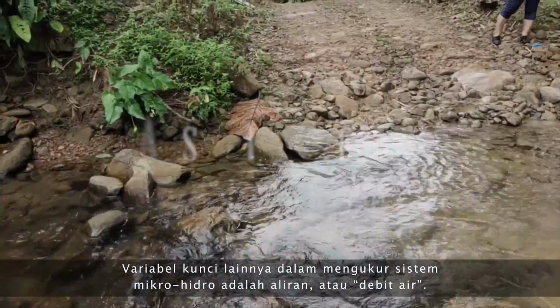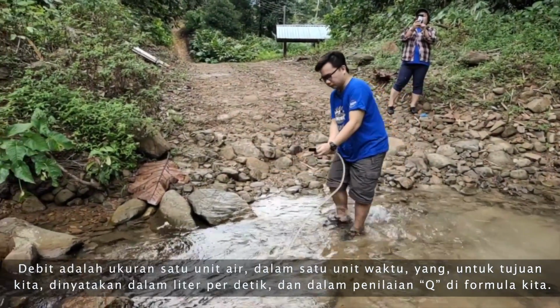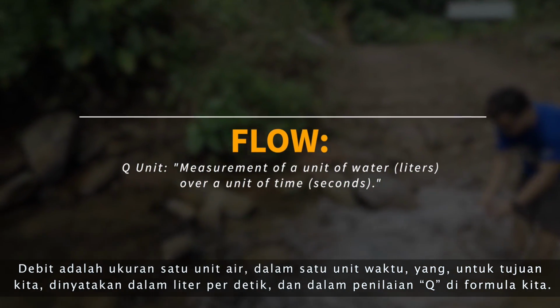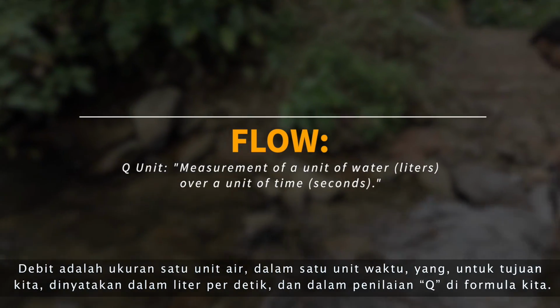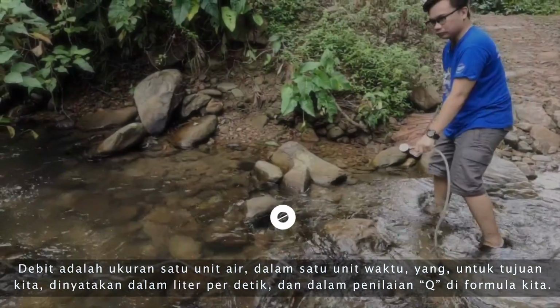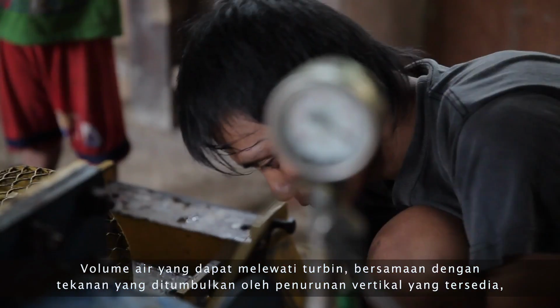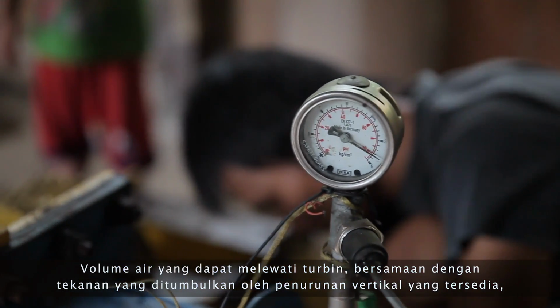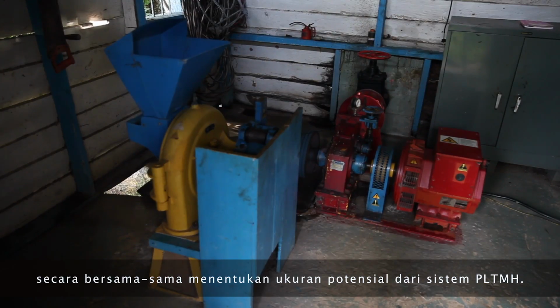The other key variable that factors into sizing a microhydro system is flow. Flow is the measure of a unit of water over a unit of time, which for our purposes is expressed in liters per second, and in the units Q in the power equation. The volume of water that is able to pass through the turbine in conjunction with the pressure generated by the vertical drop that is available together determine the potential size of a microhydro system.